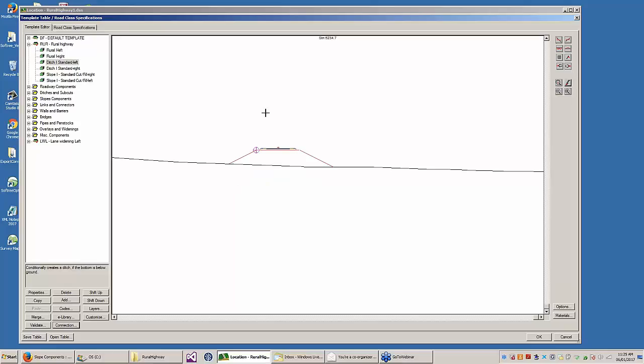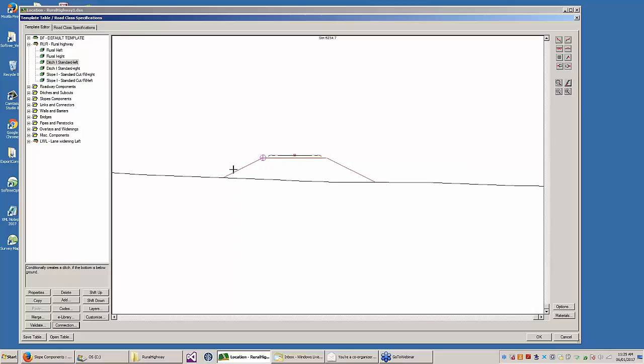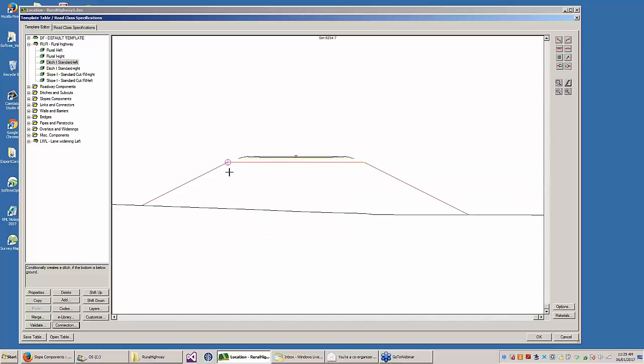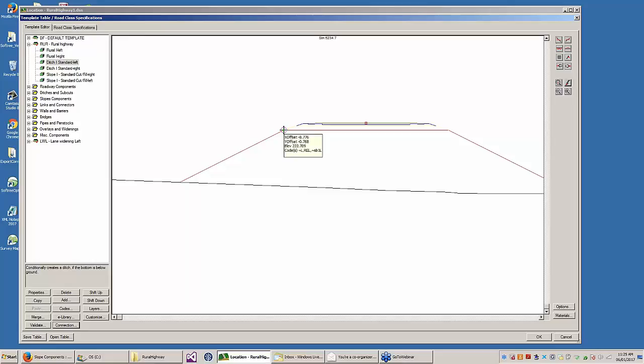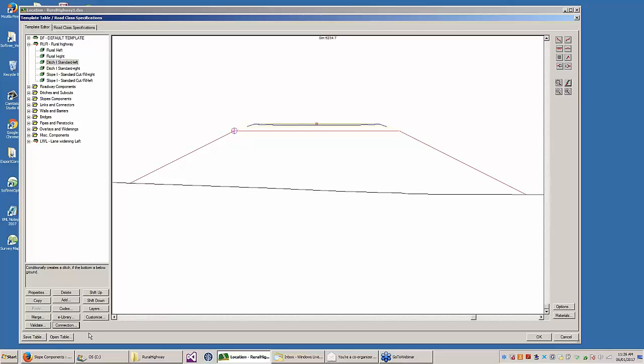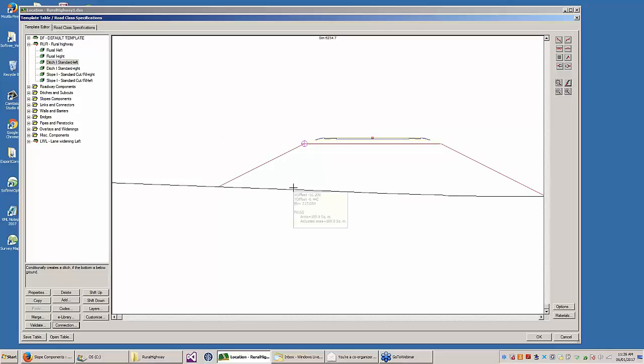Let me talk a little bit about point codes. So we saw that templates have parameters, and when the template's constructed, it creates different layers, and it also creates point codes. If I just hover over this point here, you can see there's a bunch of point codes at that point. The squiggly ones usually mean they're not really mainstream template codes. So here, let's just look at this one, STIL. There's a point code, and if I wanted to attach something to that point code, I could, and I would go into the connection, change the connection to point code, and change that. The point codes are available. You can report them, and I'll show you a little bit more about some of the ways to work with point codes.